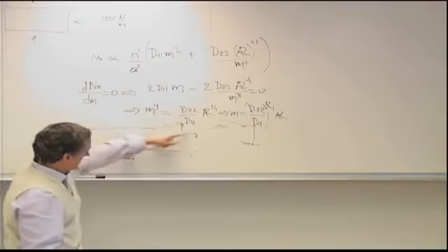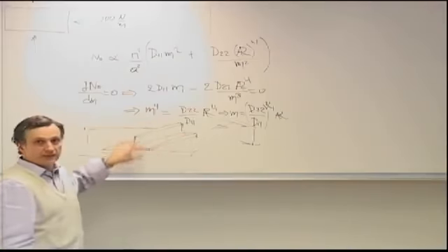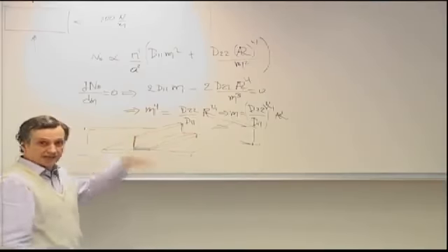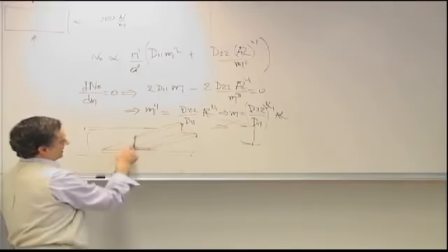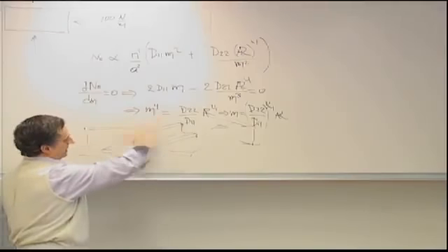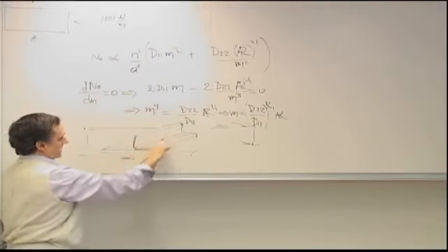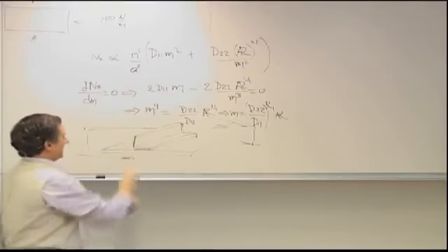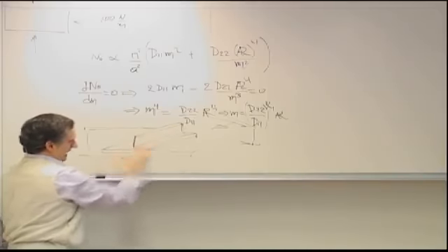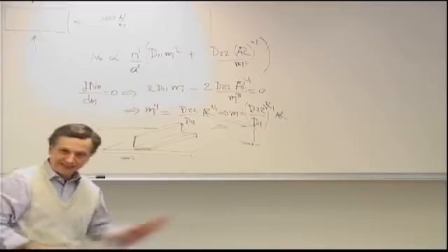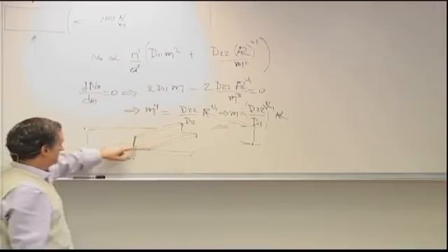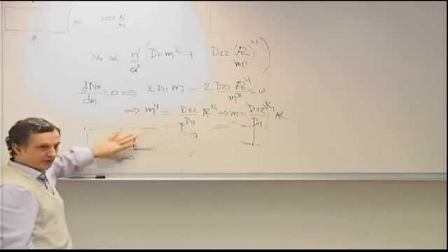And then the connection between the web and the flange essentially acts as a simple support because each member stiffens the other side. For the flange, if I think of the flange, this is vertical, so it has a very high bending inertia about this axis, and therefore it's highly unlikely that this will bend. And similarly, if I'm thinking about how this behaves, this line again is more or less simply supported. Now, having said this, these are not guarantees. You can actually come up with geometries for which this will not act as a simple support. But in general,